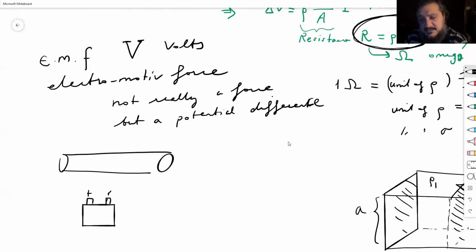So you just connect this. Okay, first of all, never connect a wire, just a wire, directly to your battery. It's dangerous, because the resistance is very small. You have to have a load. A load is a resistance. Something better than a copper wire, or you could have a really long copper wire, that would increase the resistance too, but never try this at home.